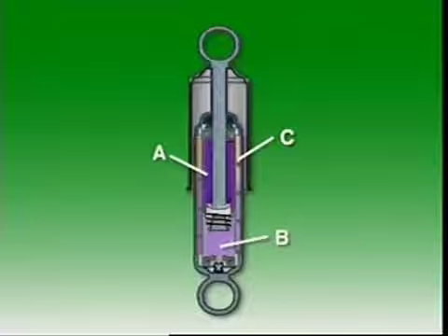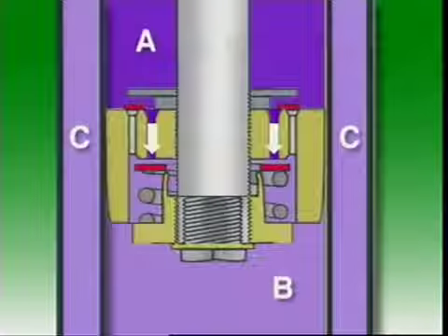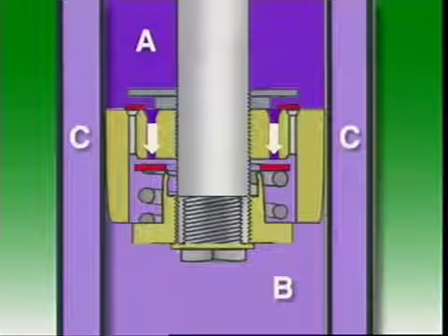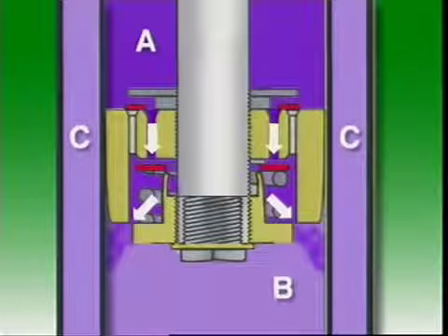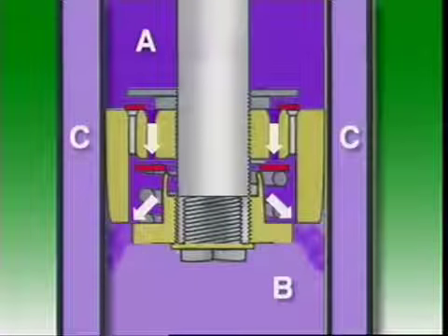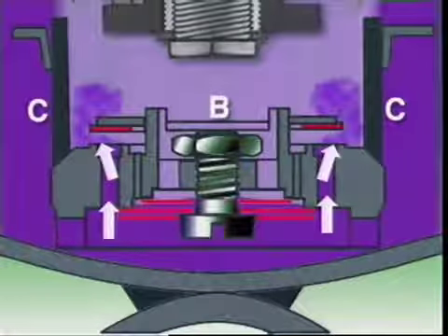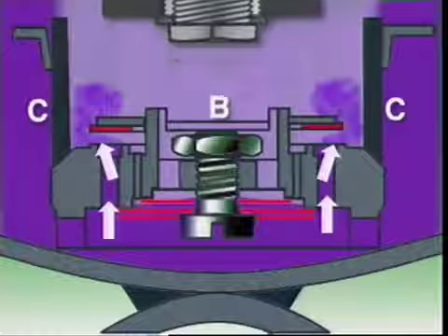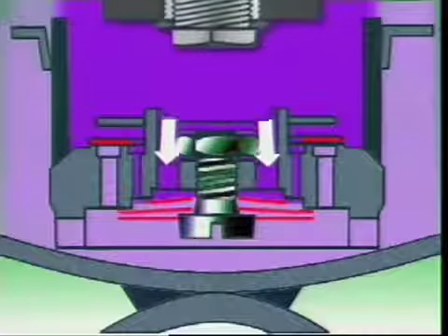In the rebound or extension phase, the piston and rod move upwards and the volume of chamber A is reduced. Chamber A becomes a high pressure area, and fluid flows through the extension valve in the piston into chamber B. However, the withdrawal of the piston from B greatly increases its volume, and fluid flow from A is insufficient to fill the space. Pressure in B falls below that of the reservoir, causing the base intake valve to be unseated. Fluid flows from the reservoir into chamber B, keeping the inner tube full. The valves provide control over the amount of force required to pass fluid through them at any given piston velocity. They can be made to open in stages according to fluid pressure.